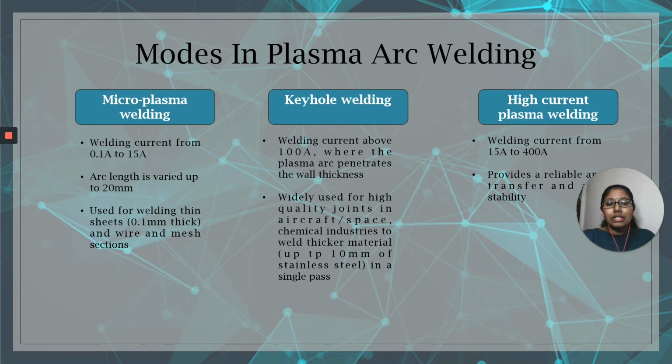The tungsten in the torch can be set in two ways in this mode. In most cases, the electrode is set flush with the end of the tip. This gives a soft arc much like a GTAW arc. The second way is to recess the tungsten inside the plasma tip. This can vary in distance but is not to exceed the recommended setting in the book. Recessing the tip provides more of a column-type arc.